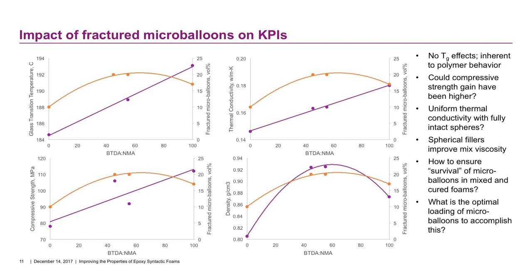So how do we improve this? How do we ensure the survival of the microballoons in the mixed composite and the cured syntactic foam? So now we've got another element to consider here. Is there an optimal loading of microballoons to accomplish this? We went with 20%. Perhaps there's a different amount which would produce more intact microballoon content and drive the properties to even greater extremes. These things are all possible.